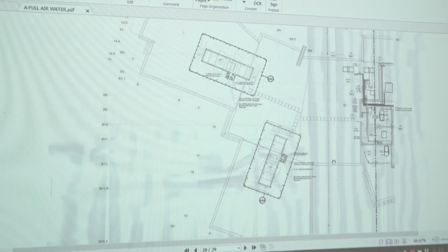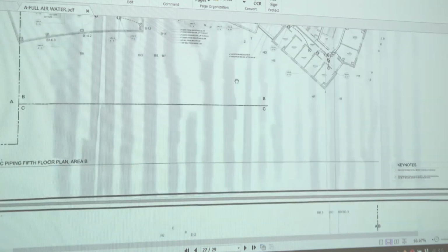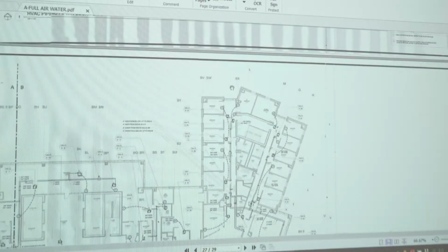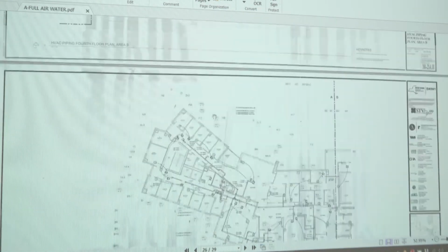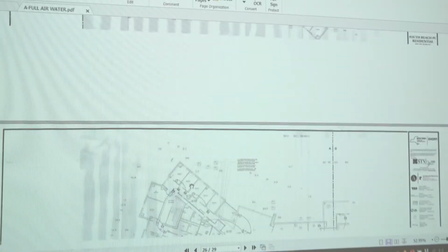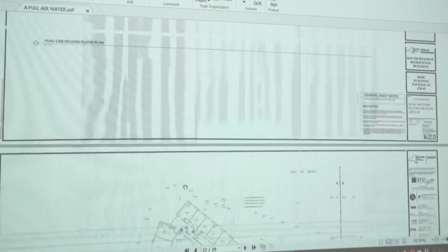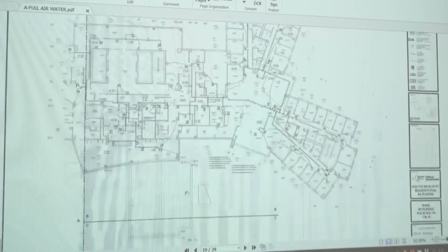Okay, so we're going to go back into looking at the overall plan view of the building and look a little more into the air handlers and the VAV boxes. Again, we're going to return back up to AHU number 1 and 7, which is on the A roof. So as the airflow leaves these units and drops down the shaft, it will be dispersed through a riser which exits on each floor, from the 5th floor down to the 2nd floor.